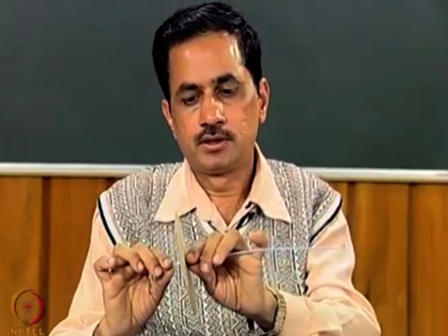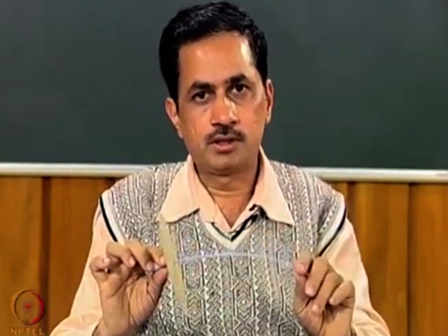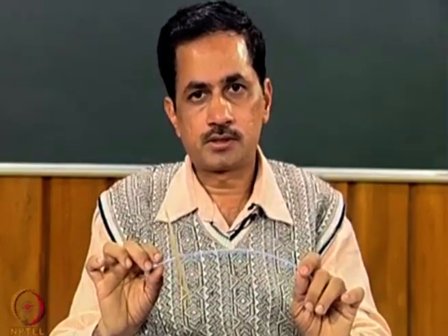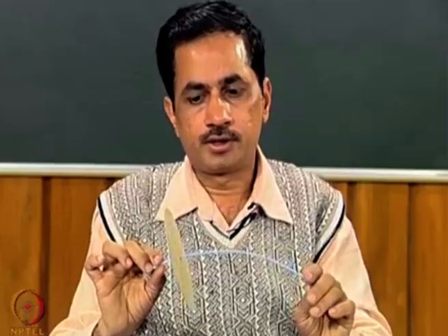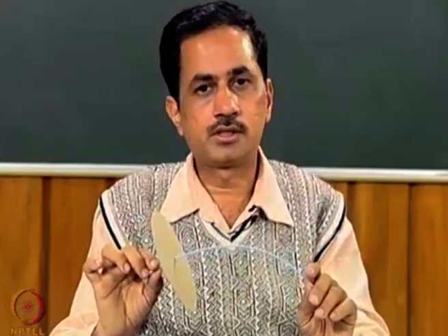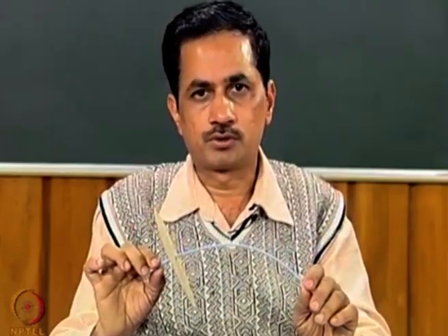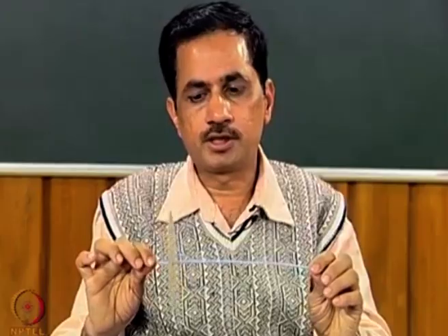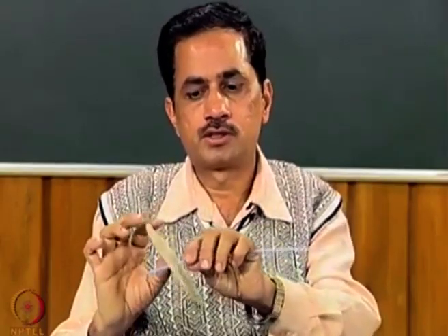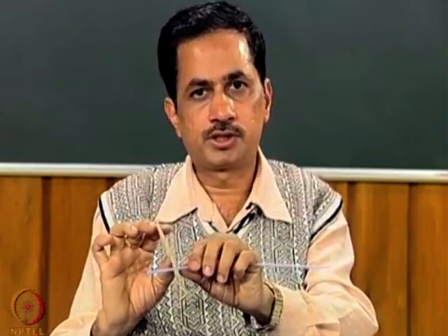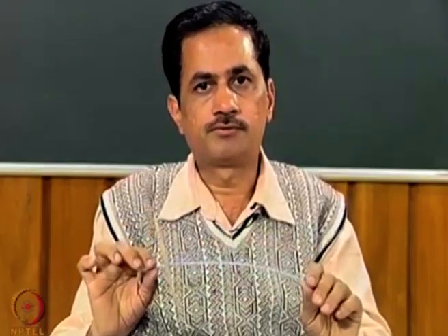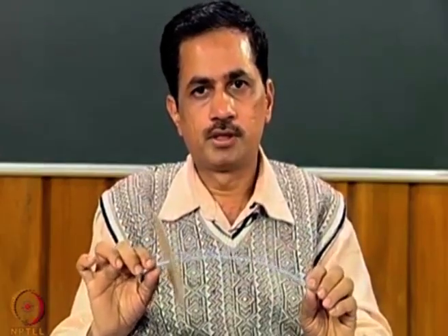In the subsequent topics, we will see that this kind of wobbling not only introduces an additional degree of freedom, but also introduces the gyroscopic couple, because this particular disk is spinning about its own axis. Because of this, it starts wobbling. So there is a precession of the disk along with the spinning, and because of that gyroscopic couple will also be there.